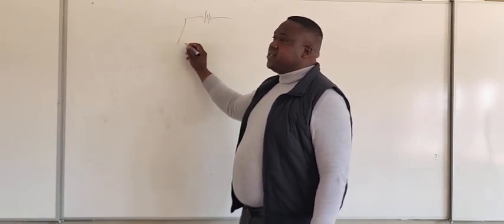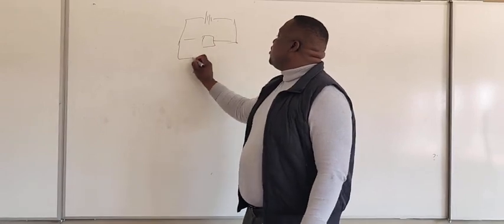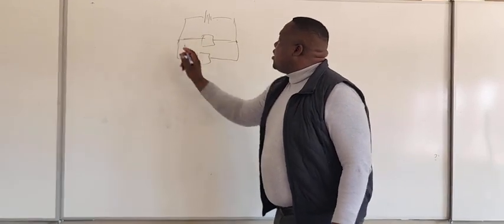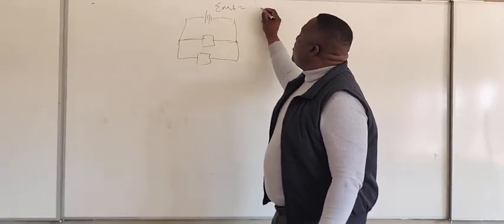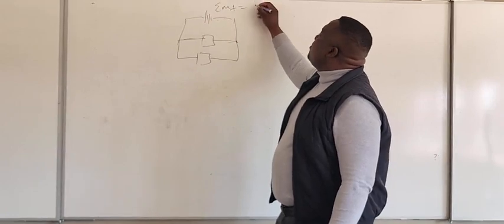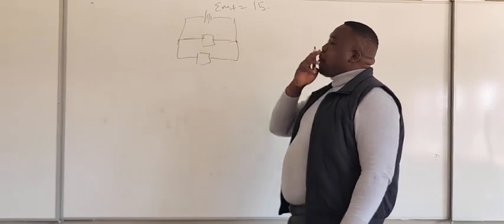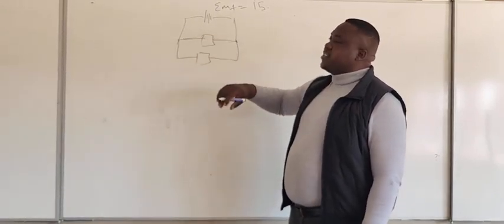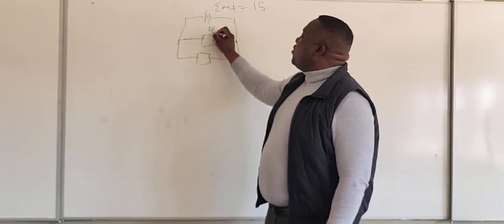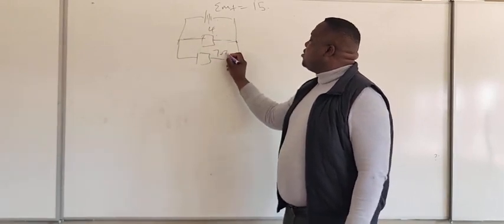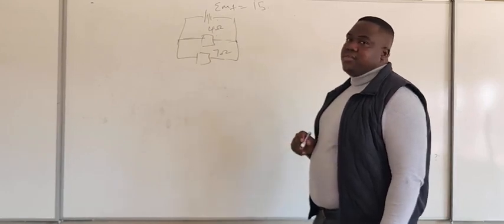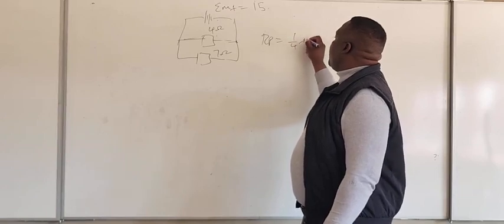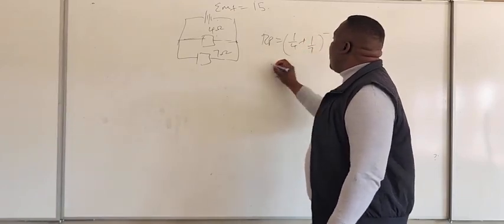these resistors which are parallel. Two resistors which are parallel. And the EMF here, the EMF is 20. Oh, let me use the same number. The EMF is 50, right? What is happening to these resistors? Let's say this one is 4, this one is 7 ohms. 4 and 7 ohms. It means the total resistance RP is going to be 1 over 4 plus 1 over 7, to the power minus 1.